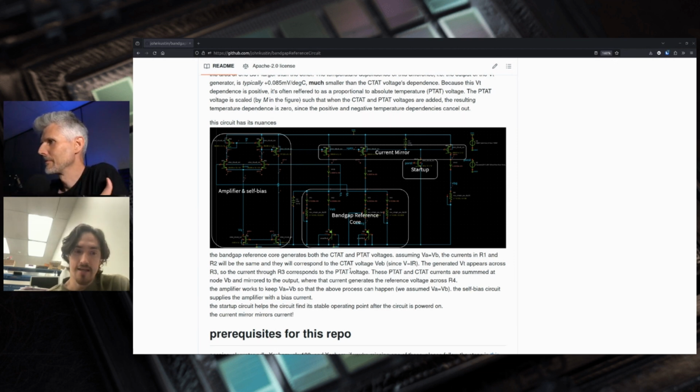It is, exactly. And I remember doing the layout. I guess we'll look at that a little bit later. It's very critical to make that assumption of a ratiometric design. You're assuming that they change the same, but you can only make that assumption if the devices are right next to each other or very close to each other. That was a detail that, as a student, didn't really connect with me until I had to place down the devices in the layout and realized, okay, this is how we're able to make that assumption of ratiometric design.